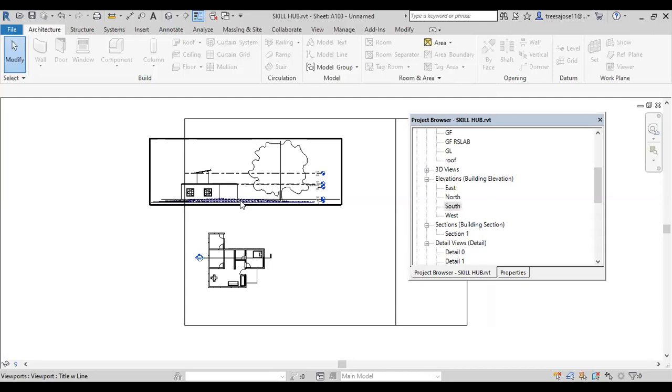That is also possible, but in the older versions, I think in 2016 and all, if you export the 3D model into AutoCAD, mesh modeling will be available. We didn't get the solid model. But from 2018 onwards, we can export the model as solid also. That is possible. Sometimes somebody is comfortable doing some extra work in AutoCAD. In that case you make the major models in Revit, and maybe somebody else can do everything in Revit itself.